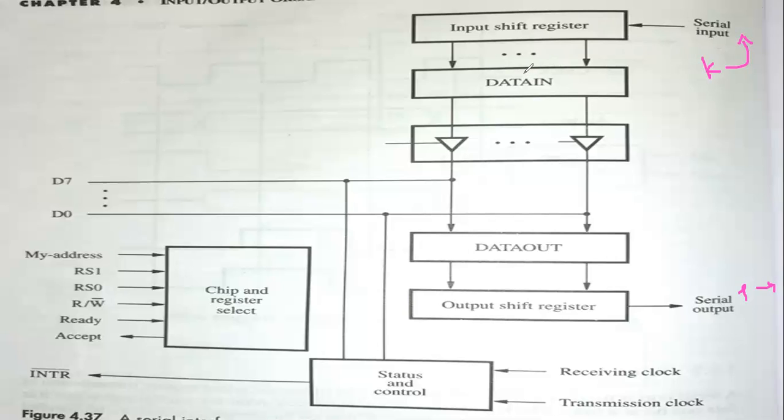So what we do, we use one more buffer, a shift register we are calling it. What it does is, it just collects the bits, it has some capacity. Feel that here we are using a total of 8 different lines, right? So we have a capacity of 8 bits to store inside this shift register at a time. Continuously it will be transferring one bit at a time.